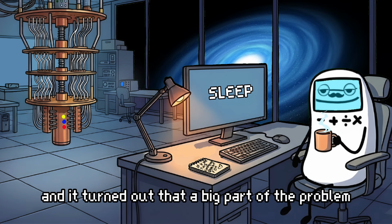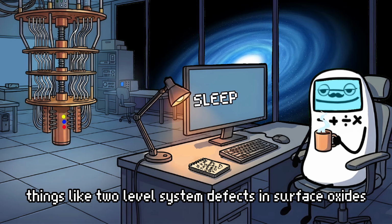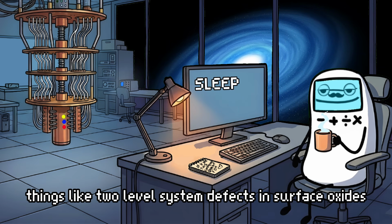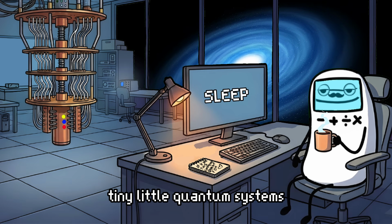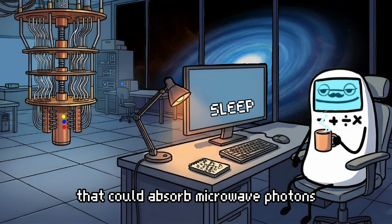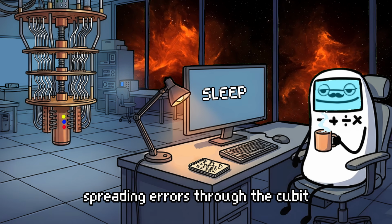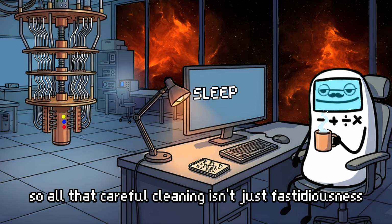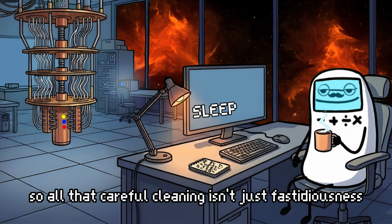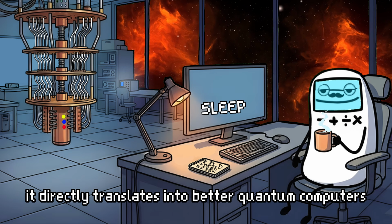And it turned out that a big part of the problem was microscopic defects at surfaces, things like two-level system defects in surface oxides, tiny little quantum systems that could absorb microwave photons and then release them back in a random way, spreading errors through the qubit. So all that careful cleaning isn't just fastidiousness, it directly translates into better quantum computers.